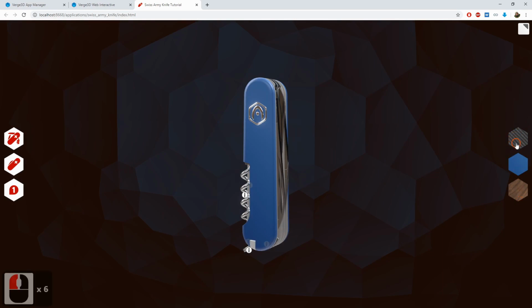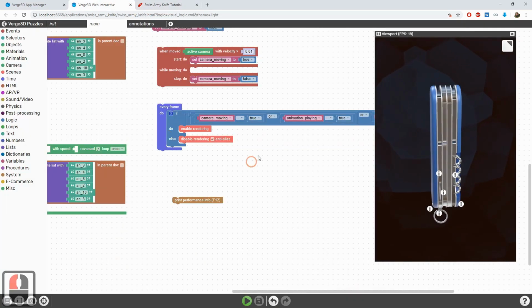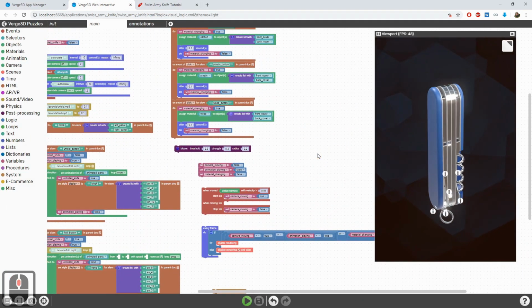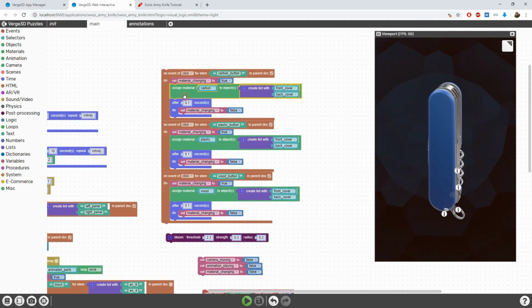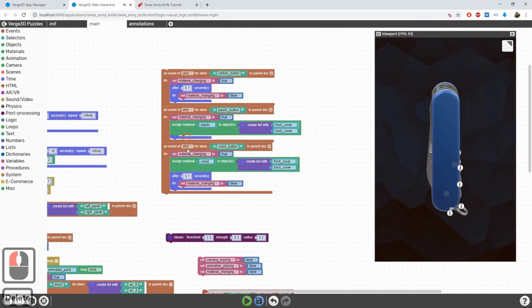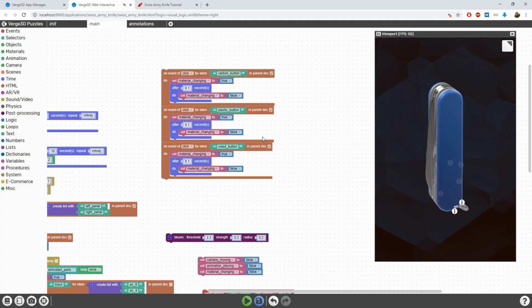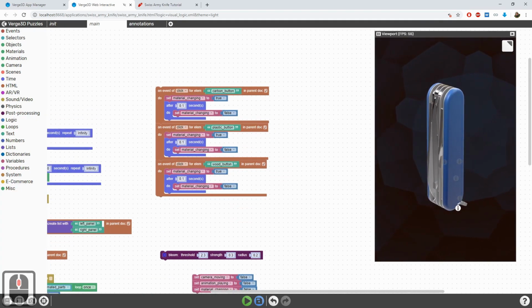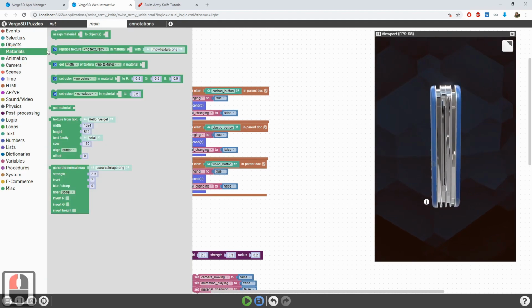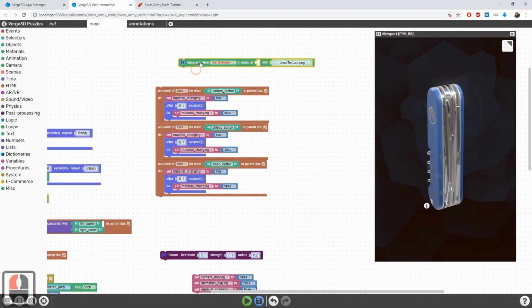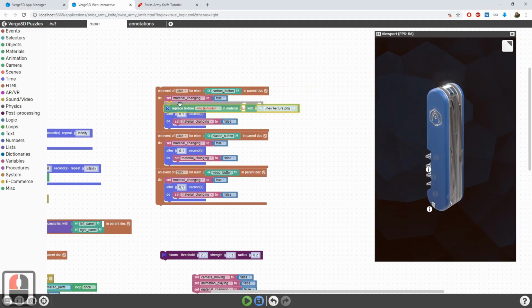However, the configurator buttons no longer work since we deleted the swatches. Let's fix this by modifying this group of puzzles responsible for swapping materials. Remove all assigned material puzzles. We'll be updating a single material instead. We'll be doing it through a puzzle called Replace Texture.